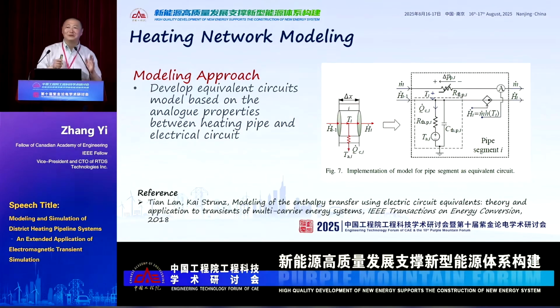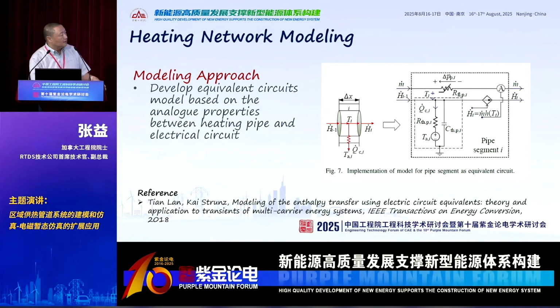So we are not power thermal engineers. So I have tried to explain this some in English and in Chinese. For that, then we can develop this model. We have this parallel part. This part is the loss, the heating actual radiation, or conducting to the ambient, to the outside environment. And this is the heat or the energy, which is a capacitor to store in the fluid flow itself. Then anyway, for that, this paper tells you exactly how to do that.